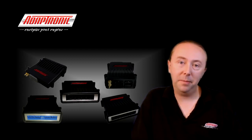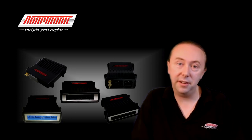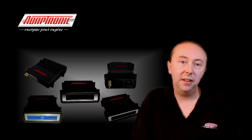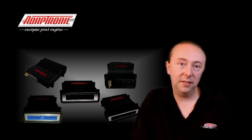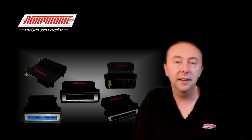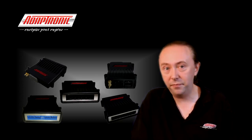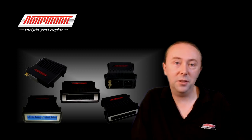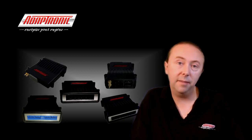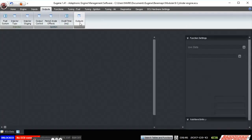One final point about the outputs page. Because the modular ECUs use switching mode injector outputs, during the off time while the injector is still being driven, that is when it's being pulse-width modulated, the recirculation current has to go back into the 12 volt supply. To keep that current loop area as short as possible, we recommend, and in fact this is shown in our wiring diagram, that the injectors and the power supply for the ECU get their power from the same source.